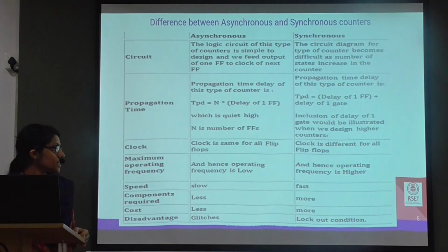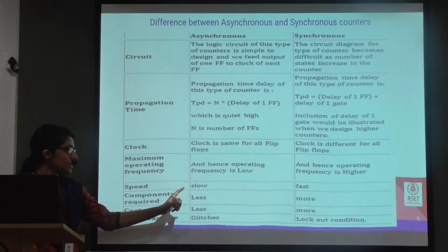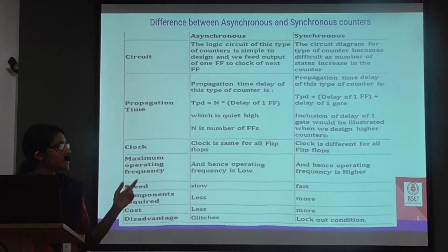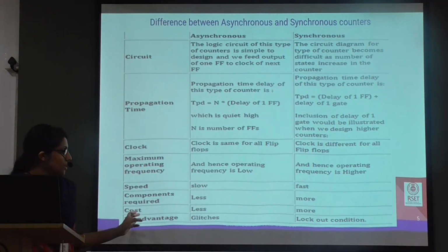Now the speed of operation for asynchronous, since it is one flip-flop after the other, is lower, while in synchronous, it is faster since the clock is provided to all the flip-flops at the same time. The components required for asynchronous are fewer, while in synchronous they are more. Because of that, the cost will be lesser for asynchronous and more for synchronous.